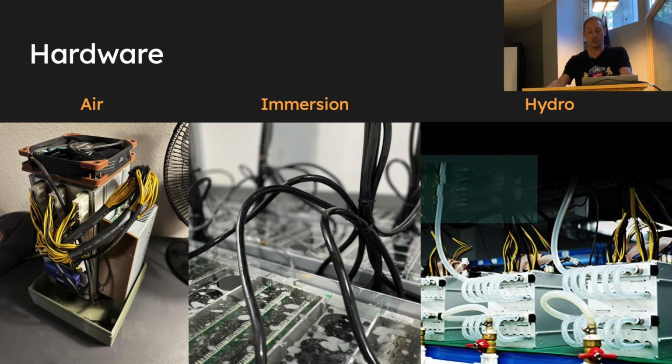The whole machine is submerged in fluid. It's also very heavy fluid. It's thick. It has what's called a high specific heat capacity. It's viscous. The specific heat capacity means it takes a lot of energy just to change the temperature of that fluid. So it's like trying to pick up a heavy weight takes more energy, right? Same thing there, and it's conductive, so it has a higher conductivity than air.